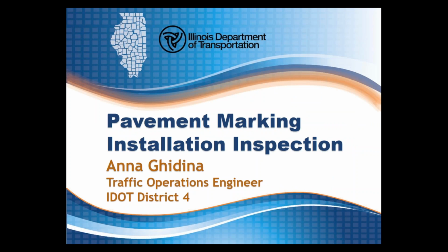Thank you, Carmen. For markings to reach their expected service lives, as Kyle described in his presentation, they must be installed properly. At the back of IDOT's pavement marking selection, installation, and inspection manual are several inspection check sheets for materials currently approved for long line pavement markings, as well as one inspection sheet for installing a groove for recessed markings. Criteria listed in these check sheets comply with IDOT standard specs for road and bridge construction. For this portion of the webinar, I'll be describing recommended tests and measurement tools for several of the inspection items.